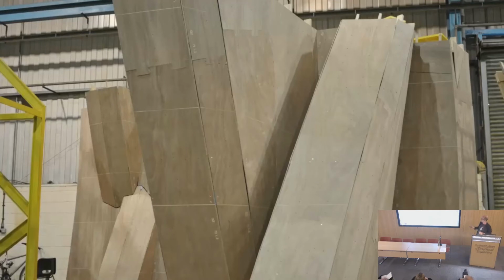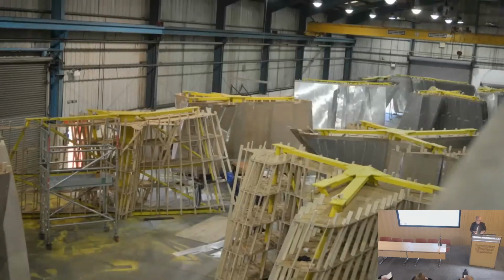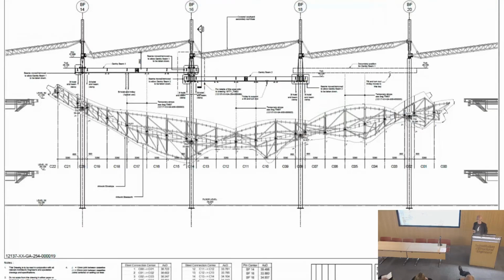So these screw holes were pre-drilled so that the people drilling them on would lie over a bulkhead that's behind. So you can build this sort of craftsmanship quality into the design, and really aid hand assembly. And some of the stuff I'll show later is more automated assembly. So this was digitally created parts which were then hand assembled, but in such a way that the thing jigged itself. And it had enough accuracy and coordination in it to make it fit together and make it so you didn't need hundreds of drawings.